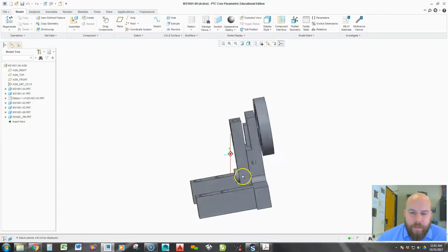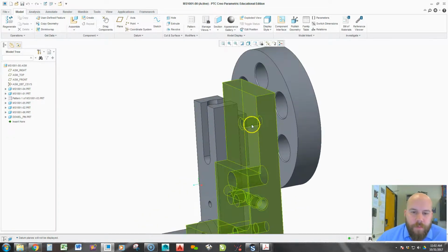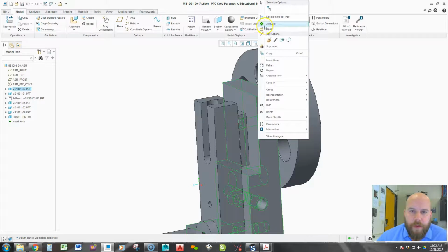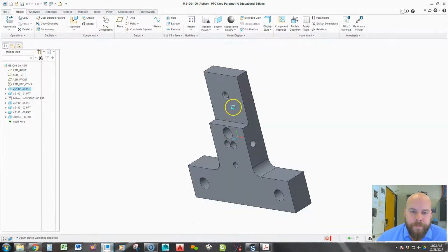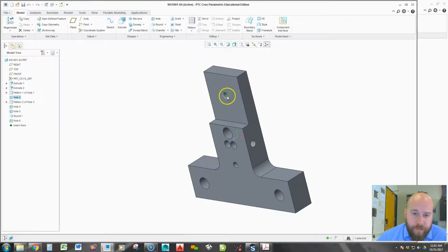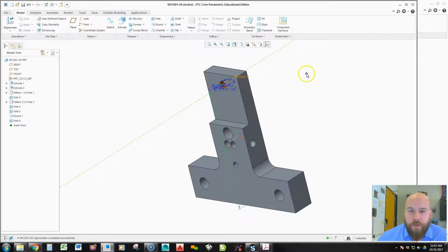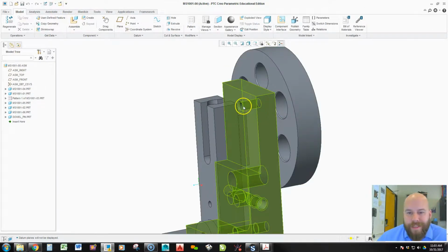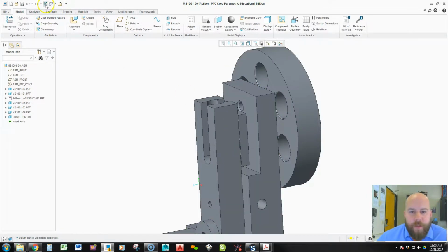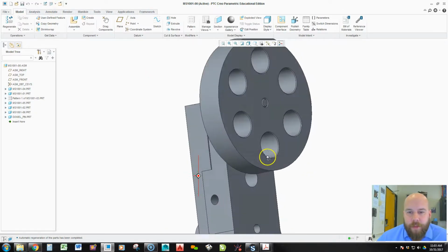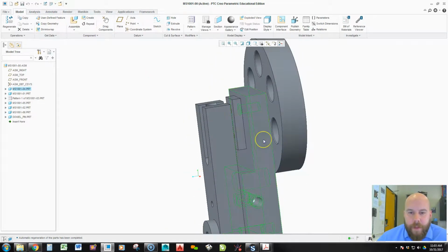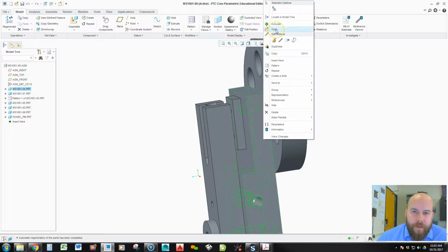The reason I like them personally is because now if I move any of these holes, for example, if I open my frame up and I change my design and I say, well, you know, this actually needs to be not quite that much, but this actually needs to be 2 3/4 up here. I regenerate this, I close it, you can see my holes moved. I regenerate my assembly, look at that, everything moved with it. Okay, so it can be a little bit of an advantage.